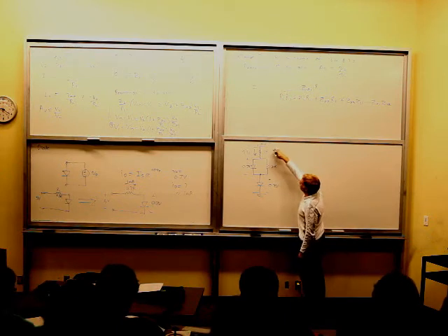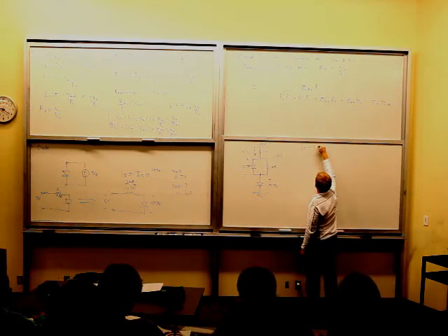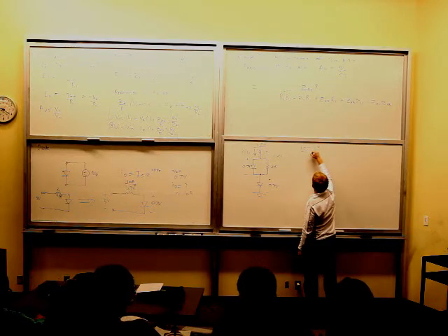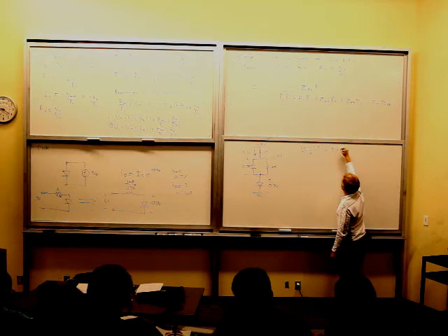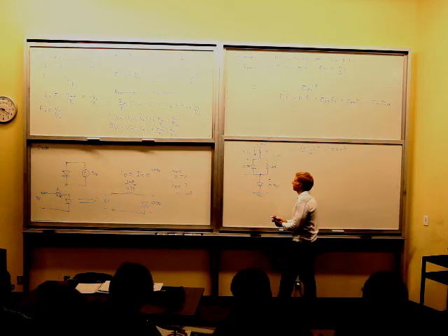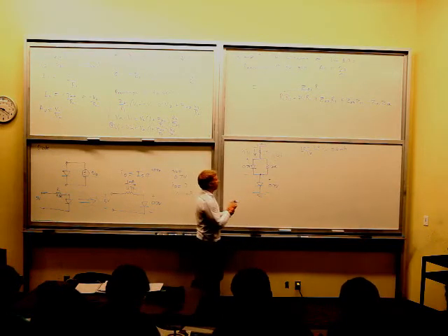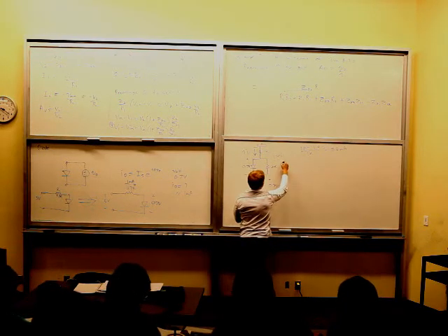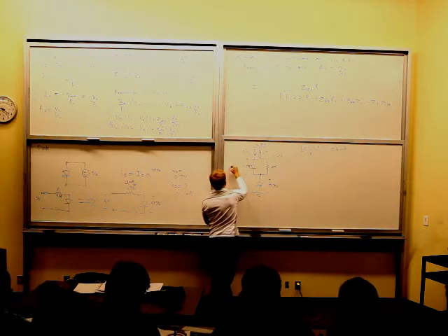So we could say, what's the current going through that resistor? I could say 10 volts minus 1.4 volts divided by 1K equals, I guess that'd be 8.6 milliamps. Yeah, that's so easy. Right? And then part 2 of the question could be something along the lines of, what's the current through this diode here? Let's call this here ID1.